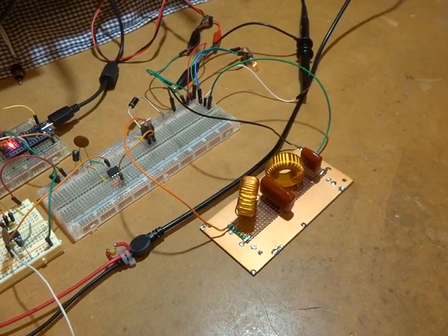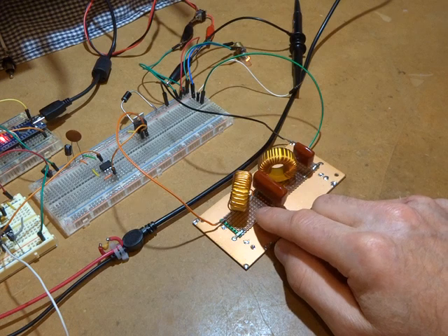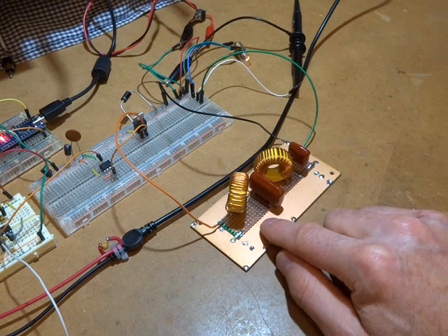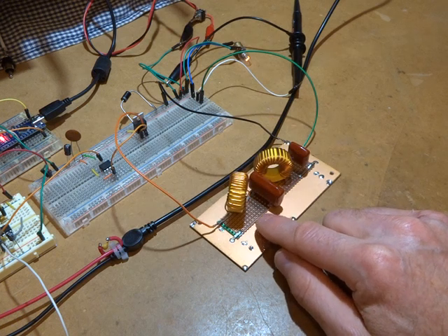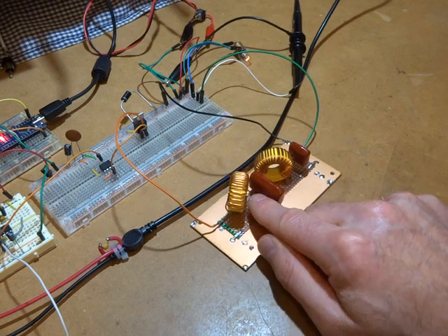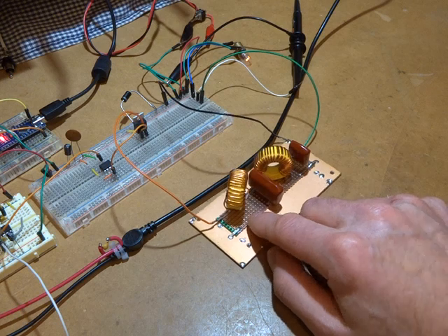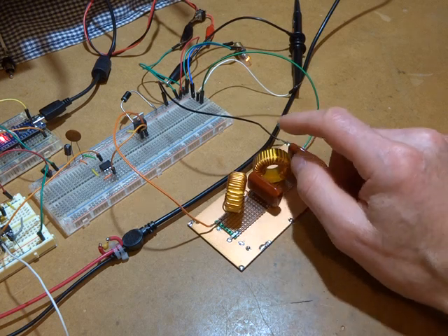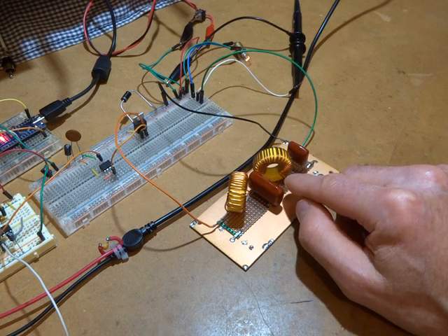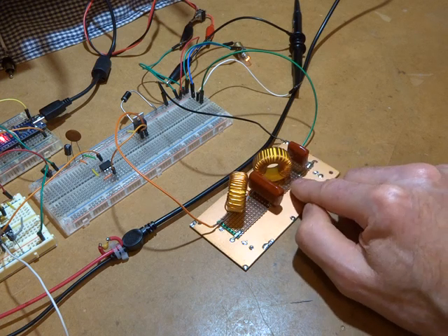Now I was quite lucky. It seems to be quite common to use a T106-26 core for these. For the higher power transmitters, you do need to provide quite a bit of current. So that's why we've got the big core here and the heavy gauge wire there. I was quite lucky some time ago to buy some surplus chokes. I'm not quite sure where I got them from. There's a whole bag of them, but it just turned out that they were actually T106-26 cores, pre-wound in some cases with 50 odd turns of quite a heavy gauge.